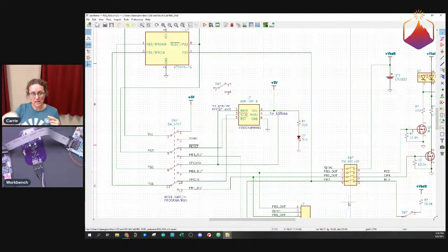After each of those 3 parts, it turns this pin, right now it's attached to blue, on our setup here it's attached to green, and instead of it being an output that controls this line, it switches it to be an input, and it essentially reads the voltage on that line.